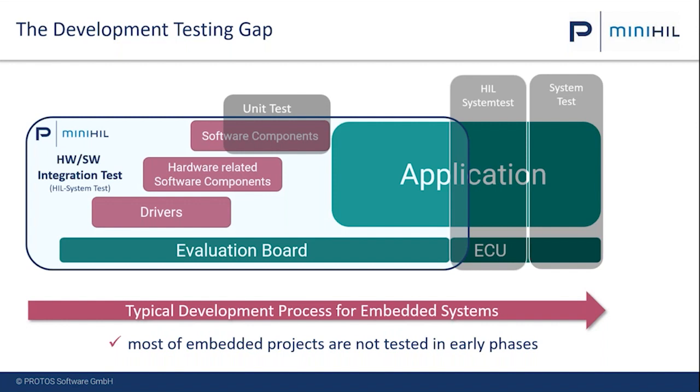So what we focus on with the mini HIL is the early phases of the development. While you're developing over the complete process, basically, we focus on what we call hardware software integration test. So on the real microcontroller with the complete software stack you're providing, we make a black box test for your application. So that's the basic idea.